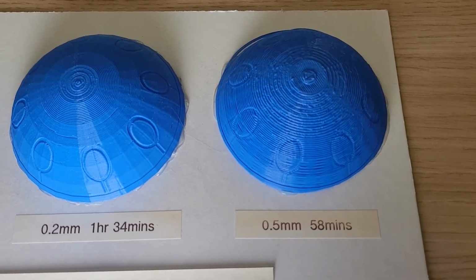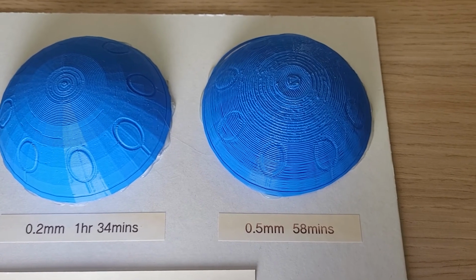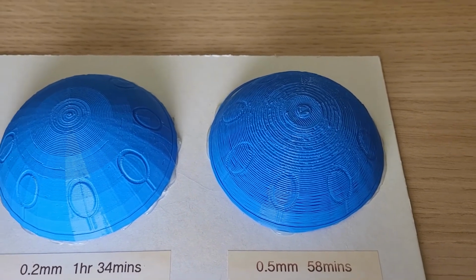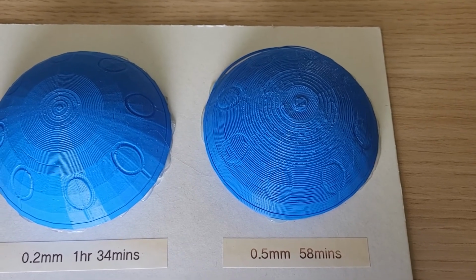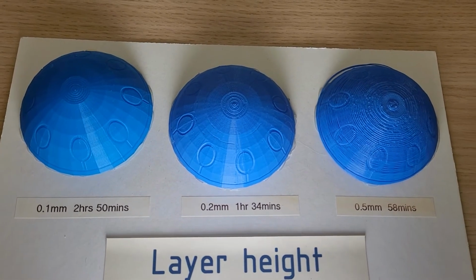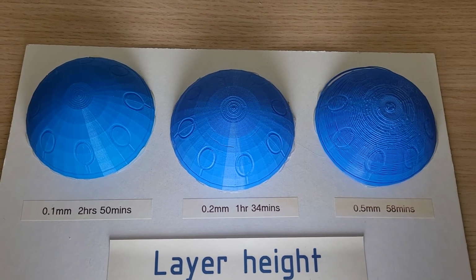And if we look at quite a rough draft setting, this is a 0.5 millimeter step, and you can see that's taken 58 minutes, and you can see it's pretty rough. You wouldn't want to use that for a finished presentation model. You wouldn't want to be filling and sanding that. So there's a quick look at the different layer heights, how long they take and what they look like.